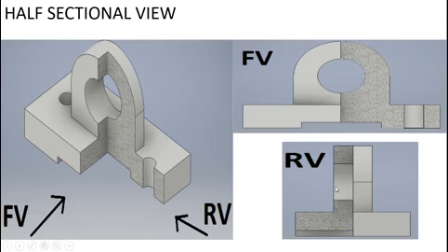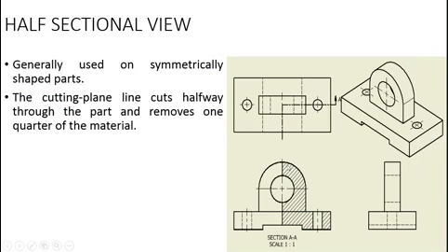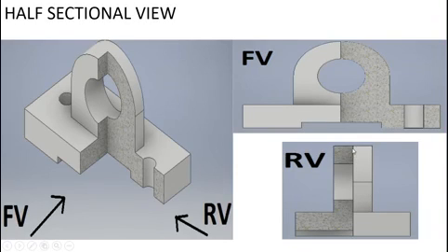Similarly, if you are looking from the right view, this is what you will see: one half which is rough, and the other side which is smooth. So this is the view in orthographic view, and this is where you will be hatching. You will be hatching here, and as a result, this is the answer for section AA. Here we didn't make section BB, but it will still look like this one, where we will only be hatching one side or one half of it.